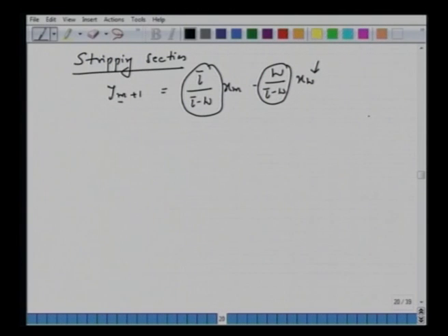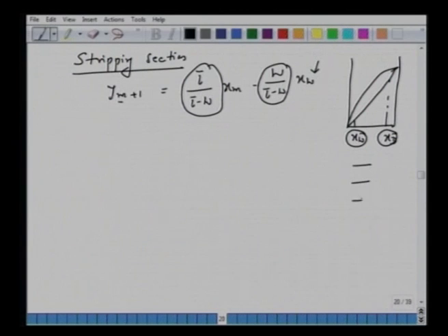So that's what we said in the McCabe-Thiele method. Even if you know the slopes, but if you do not know the compositions of the 2 products, you cannot draw this graphically. So neither xt nor xw is known to us. So we are trying to solve analytically, and these equations can always be programmed for every stage. So you have to realize that for all stages above the feed, and all stages underneath the feed where it enters, we can write down 2 equations.